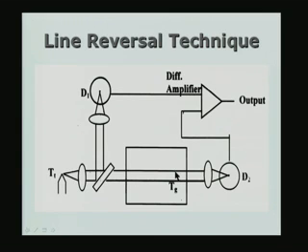So, at the same time I am able to see the target directly, like what I explained earlier. So, direct view, and the other one is through the gas, and what I have to do is vary the temperature of the target by using some arrangement, like a filament whose current is varied systematically. What you will notice is that if you connect the outputs from detector D1 and detector D2 to a differential amplifier, the output will be 0 under the condition of line reversal, incipient line reversal. If the output is positive, then we know that the target is at a temperature higher than the gas temperature.